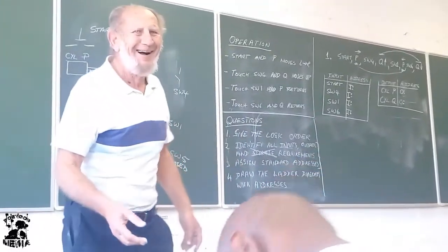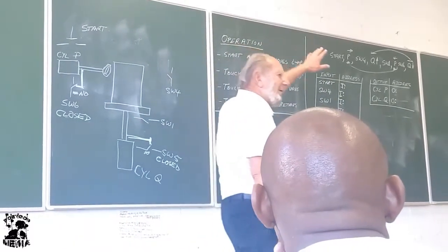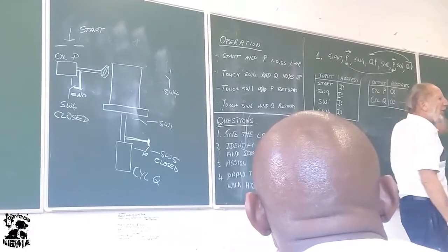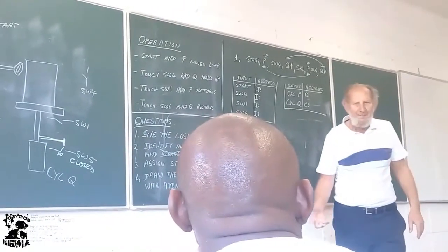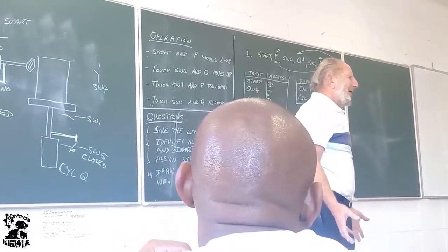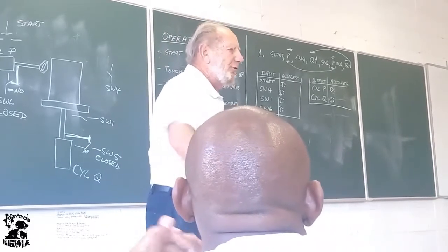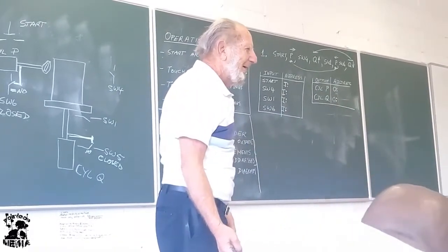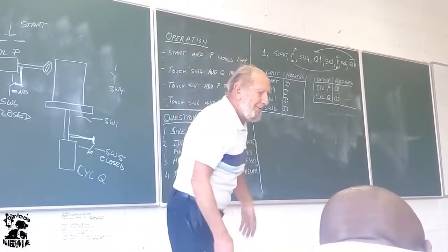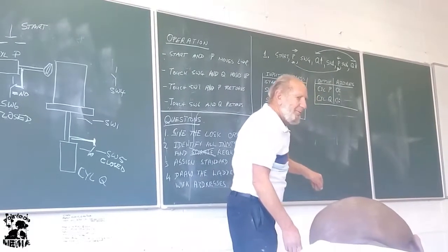Okay. Now, why I told you that is when it comes here to the design. After the I colons, after the O colon, you get the rack number. It's your design, you can use what you like. The rack number must be what? 00 or 01 or 02 or 03. Okay? What rack number do you want to use for the input? 01. All four of them? Why not?